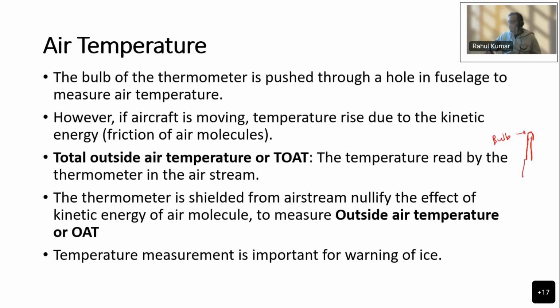You can use a digital one or a mercury thermometer, whichever, but you have an end which is sensitive to temperature. So that's your bulb. The bulb of the thermometer is pushed through a hole in the fuselage of the aircraft, like that, and then you have your aircraft body, right? So it is pushed outside.